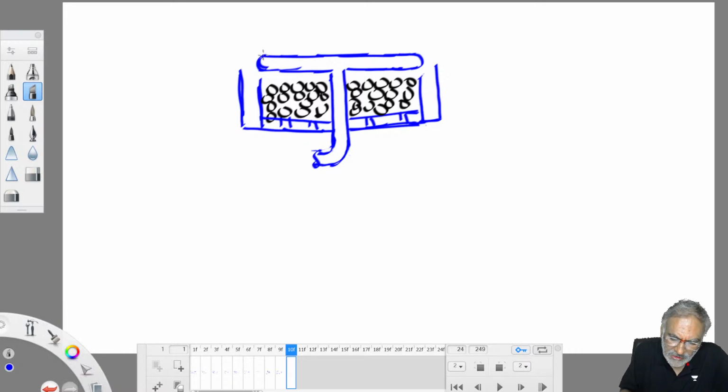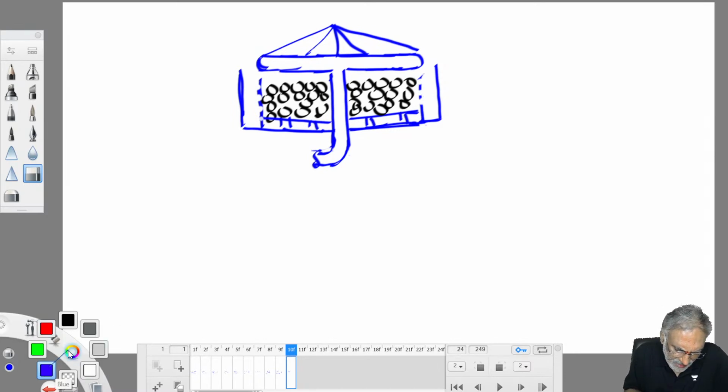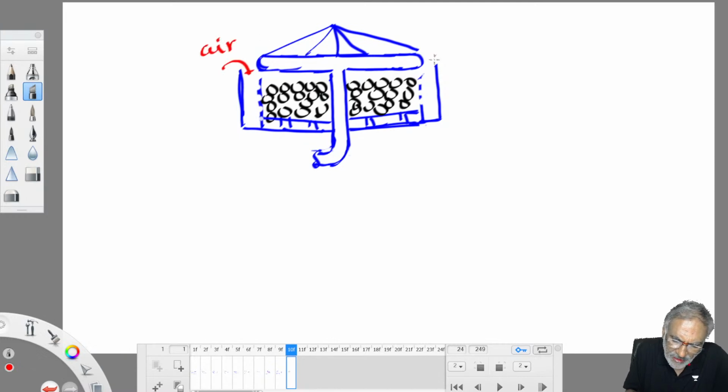So this is attached like this. And here this is honeycomb. See here, oxygen is circulated. We see that there is a free circulation of oxygen throughout this. Air contains oxygen, so this is an aerobic process. Here wastewater is applied, influent is applied, Q in here. Effluent is collected from the underdrainage system.